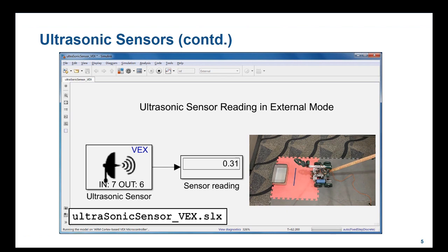We can also see some zero values intermittently. Sometimes sensors could drop values, and this scenario needs to be considered when building the algorithm. Towards the end, the sensor shows 0.02, even when the sensor is literally touching the obstacle. This is the characteristic of the sensor, since it can only measure 0.02 meters as a minimum distance.